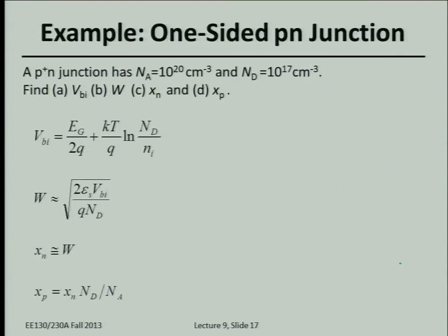Oh, great, we get to do an example, so you get an idea of the order of magnitude. Oh, good, I have the answers. Let's say this is P-type, heavily doped on the P side and moderately doped on the N side. So what is this first term here? 0.56 volts, right? It's one half the band gap divided by Q. So it's 1.12 eV divided by 2, and then you take away the e because you're dividing by Q.